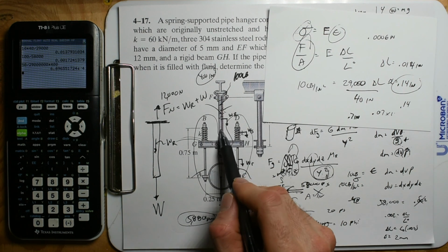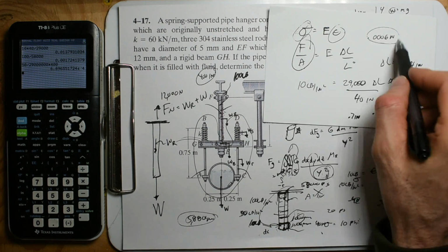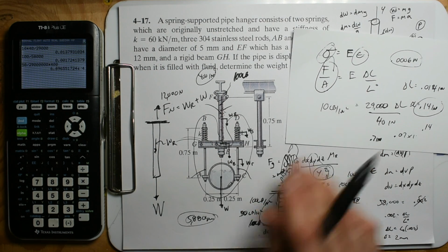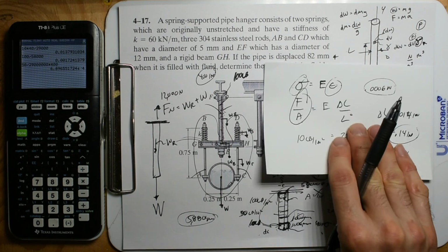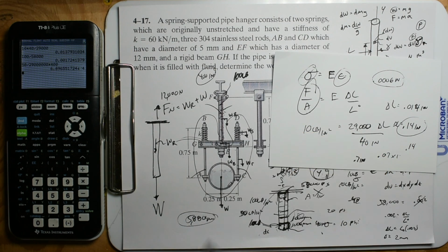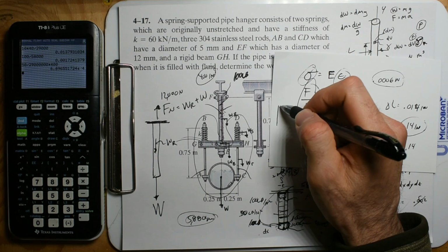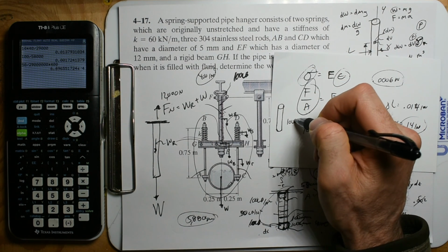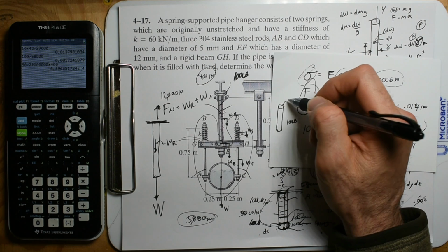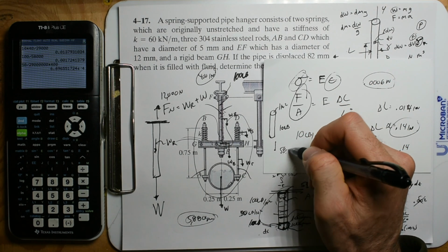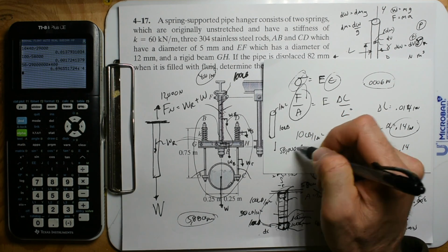The weight of something isn't going to change the displacement very much, just due to its own weight. Now, if you load up a member, hell yeah. You could have a member that only weighs, let's say, 10 pounds, but you have a cross-sectional area of 1 square inch, so I can put 58,000 pounds on that.